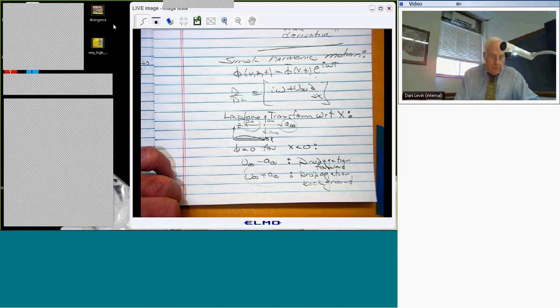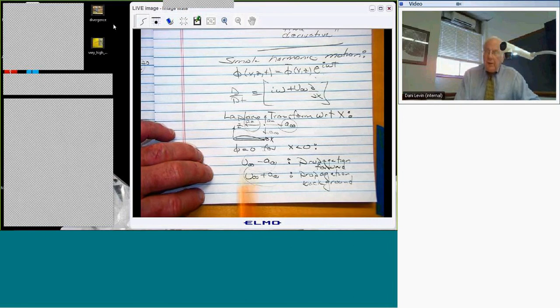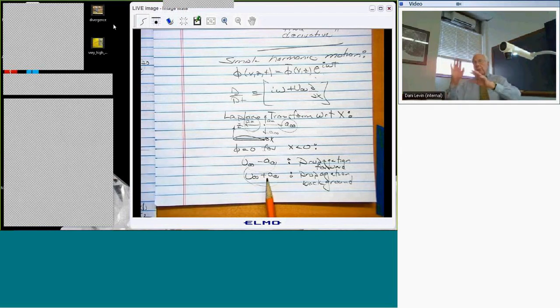You can also see another way in which transonic flow may become more complicated. What happens, of course, in transonic flow is this term becomes smaller and smaller until right at Mach 1 it goes to 0. So what I'm doing is when I'm flying through the air, I'm disturbing the fluid, and when I get close to Mach 1, those disturbances sort of build up on the airflow, right? They can't get away. In fact, what they do is they create a shock wave.